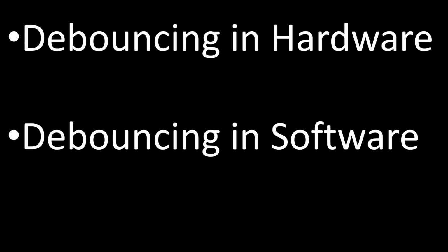Basically, there are two different ways to debounce a push button, either in hardware or in software. Since debouncing in hardware requires additional electronic components and space on the PCB, debouncing a push button in software is the better alternative.